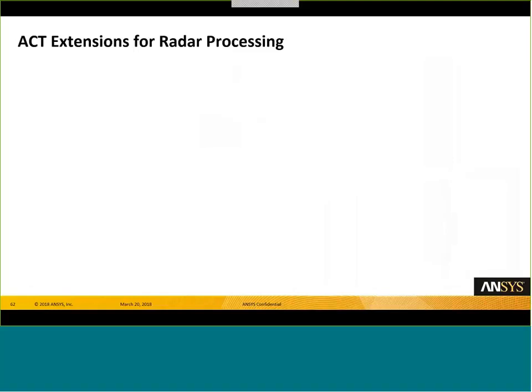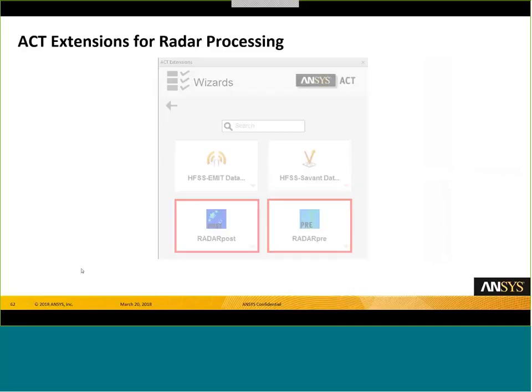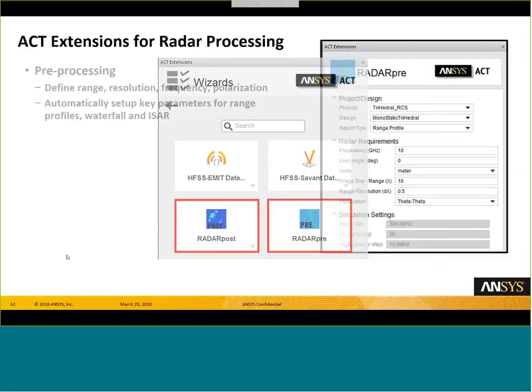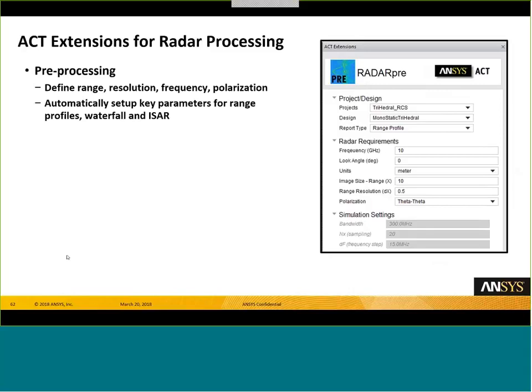So if you weren't taking notes on all of those analysis requirements that we just put in for range profiles and ISAR imagery, don't worry, we've done all that work for you, and we've done it in the form of what we call the Ansys Customization Toolkit. This works for our SBR solver as well as our full wave solvers. Let's say that you've got a monostatic problem in mind. You can just pull up the pre-processing form and define the range, the resolution, the frequency, and polarization that you want. And when you hit the go button, that analysis model is going to be set up for you and ready to go.